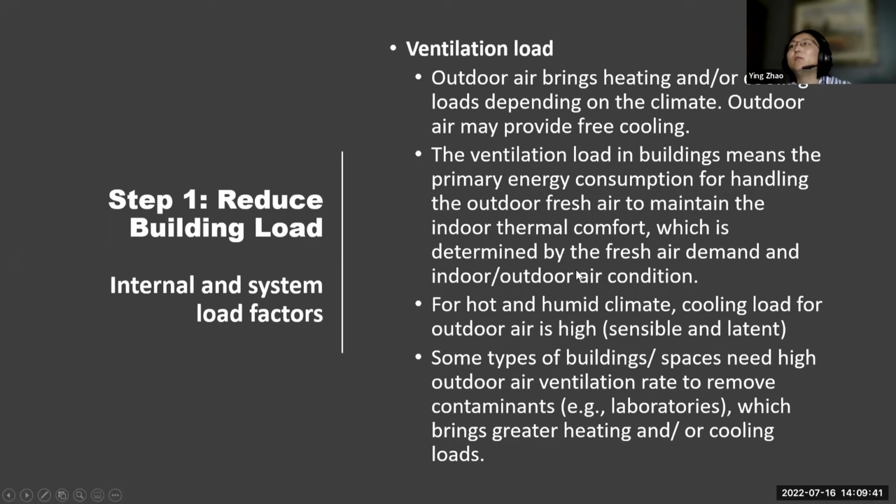And another load is the ventilation load. Because all the air brings heating and or cooling loads, depending on the climate. Although air may provide free cooling, it could also cause a heating or cooling load.